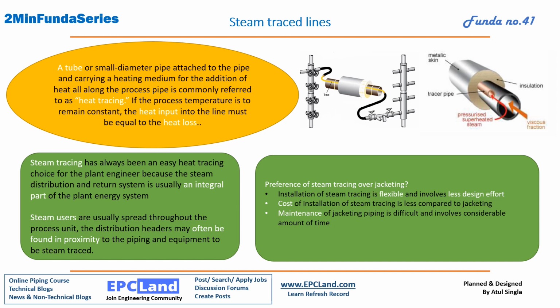Okay, why we are doing this? Because if the process temperature is to remain the same, the heat input through this line should be equal to the heat loss by the core pipe. We have to maintain the temperature inside, so the heat loss from this pipe and the heat input by this pipe should be equal, so that we can maintain the properties of the fluid inside the pipe.